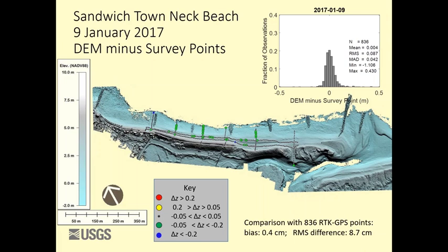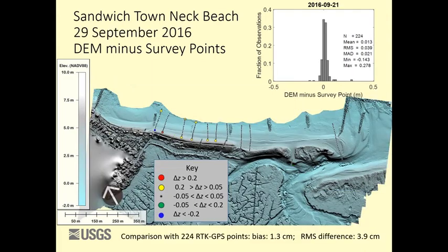You're putting a stake on sand, and you have a bubble, but the antenna can move a little. So say a couple of centimeters for all those RTK points. And what I'm comparing them with is the digital elevation model that we've extracted from the images. This digital elevation model that you're seeing shaded here is 10 centimeters. We just take the closest point from the RTK and we compare it. And that's the histogram of how different the RTK points are from our final product.